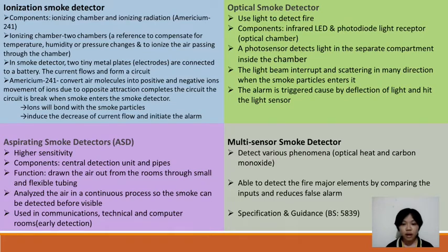Lastly, multi-sensor smoke detector. These detectors contain various sensors. It can detect various phenomena. It is able to detect the fire's major elements by comparing the inputs and reduces false alarms. The specification and guidance for these smoke detectors is based on British Standard 5839.